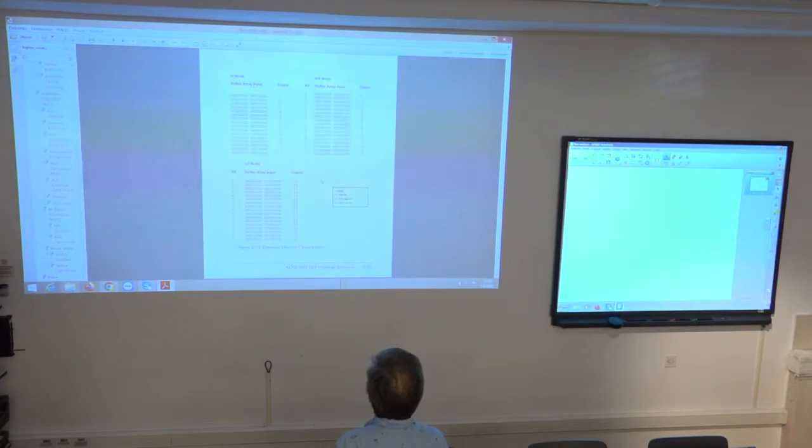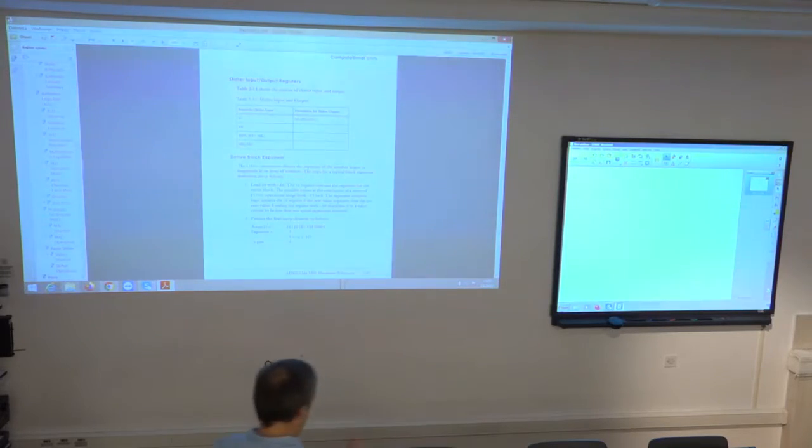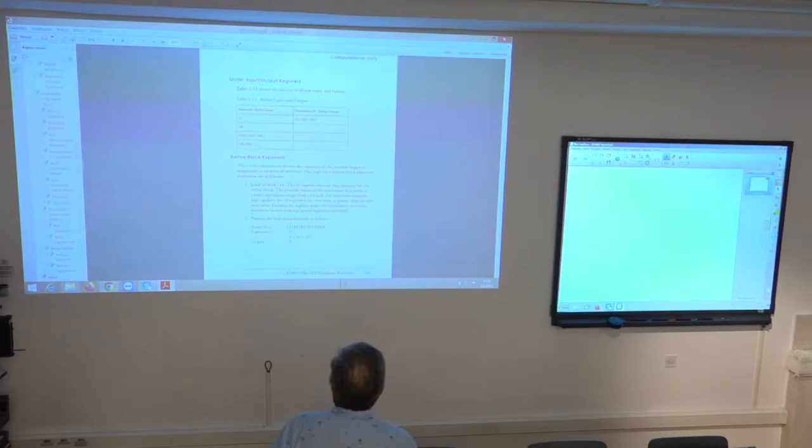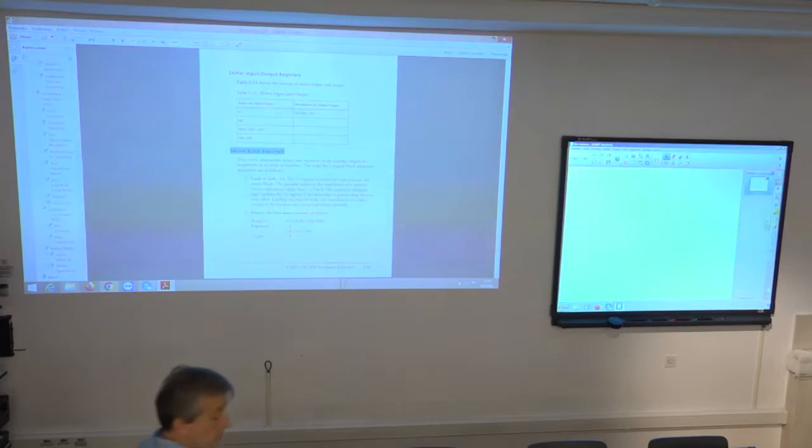There are several examples of how this exponent detection works and how it is combined with the normalization instruction. There is also one special instruction that enables detection of a common exponent of several numbers or a block of numbers. So for example, you have 128 different values, and you want to find how many bit positions to the left they can be shifted without causing overflow.